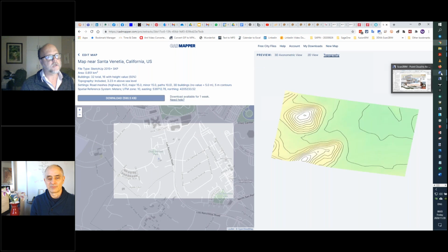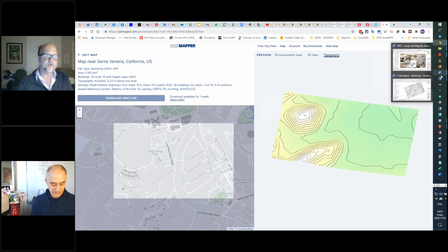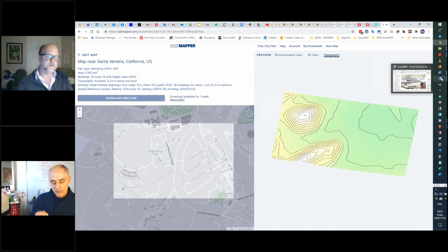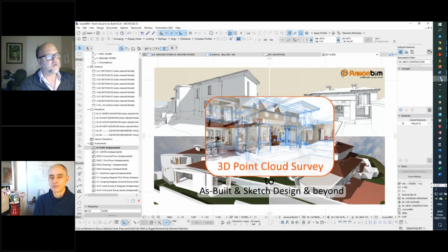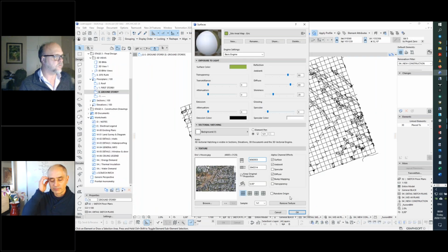So in ArchiCAD, you'll just tweak the proportions of that texture. After you see how it fits, I can see if it's overshooting or if it's starting to tile, and then it's just a proportion calculation I do to get the proportions right. And the actual 3D geometry also tells me where it sits in the lines. So let's just do this for the start.